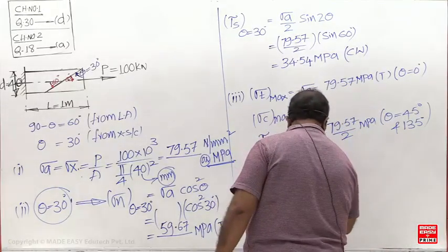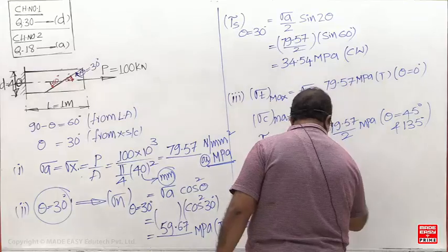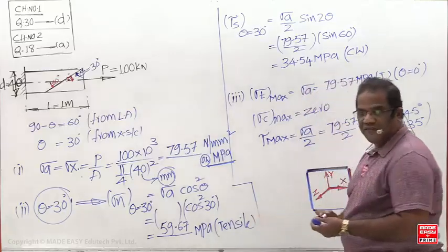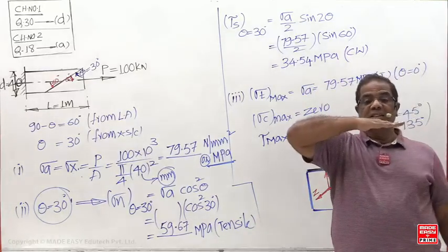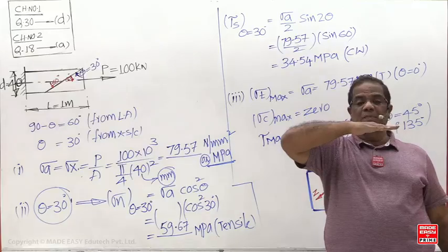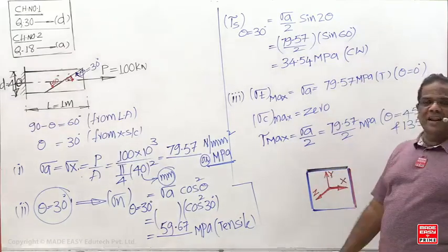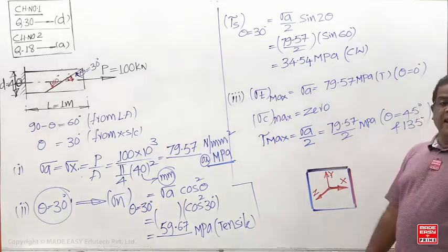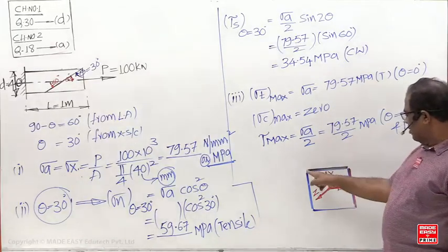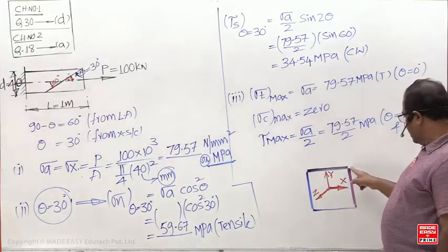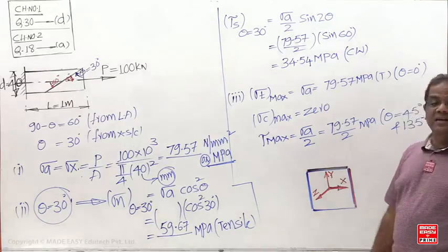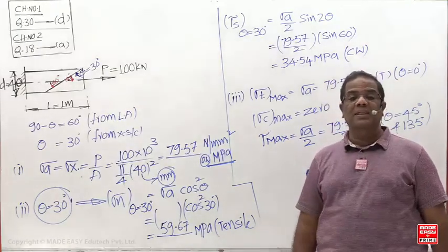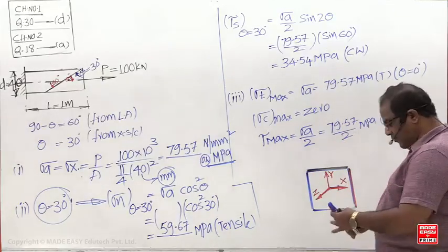This is the Y face. This face can be seen in the top view, but in the front view it becomes a horizontal line. So this black color horizontal line is representing the Y face. The red color line is representing the X face. For this line, which axis is perpendicular? Y. For this black color line, the Y axis is perpendicular to the Y face. This is the X face. And what about this blue color rectangle? Z face. In the front view you can see only one face, and the remaining faces become lines. This vertical line is the X face.